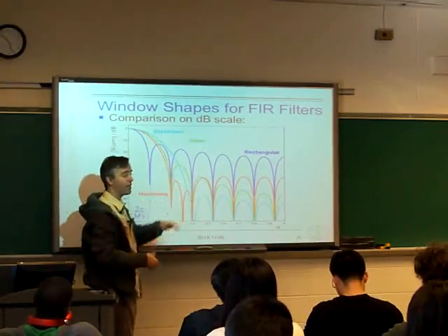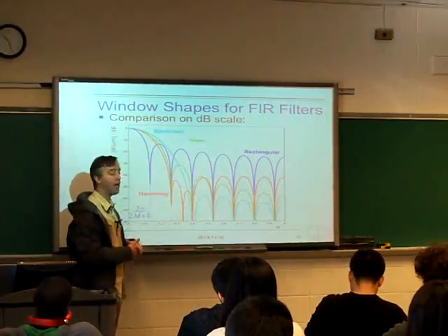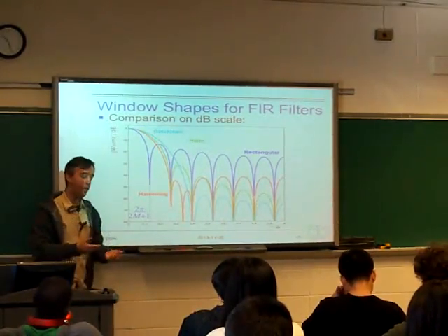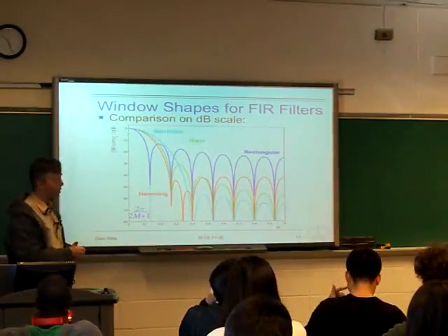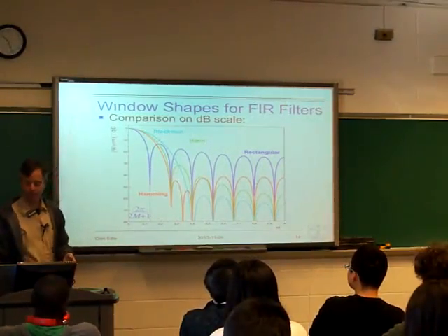This isn't exactly what the transition edge is going to look like, but these bandwidths and side lobe heights are going to determine the artifacts around the transition band, the pass band edge, the transitions.